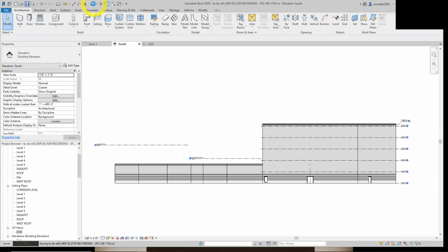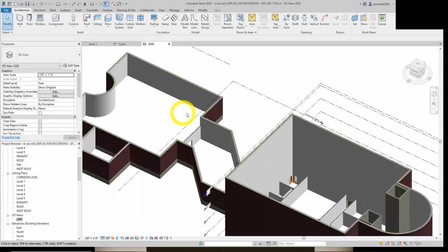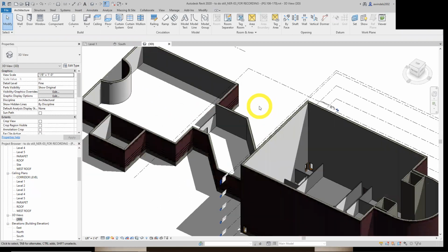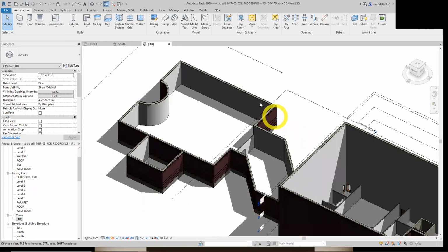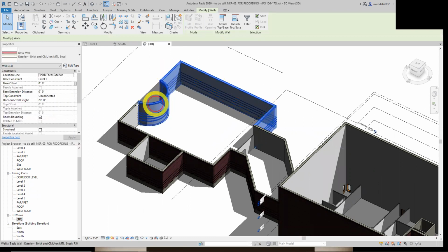And go up here. You can go here. 3D view. Let's go up to the quick access toolbar in this case. And we're going to start building up the rest of the walls to the corridor in the west side of the building. We're going to start by selecting 7 exterior walls on the west side of the building. 3D view is helpful. They recommend it, and I would say not a bad move. Bam. We're going to check this. So we hold control. We should have 7 selected.